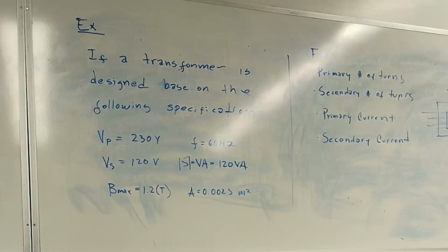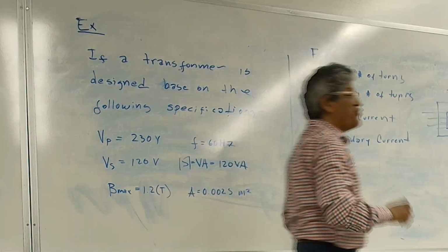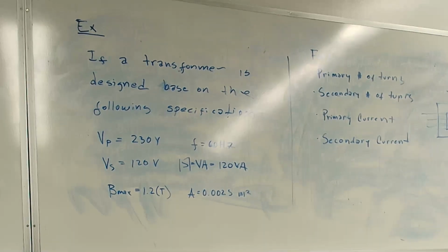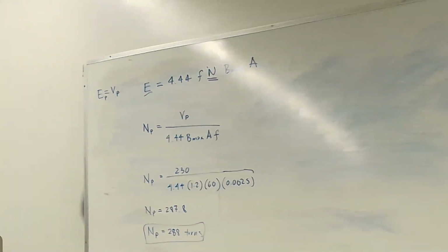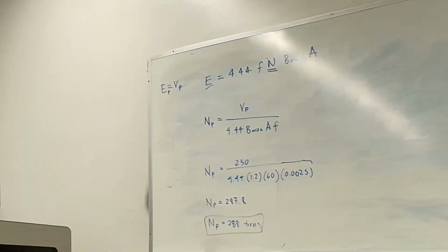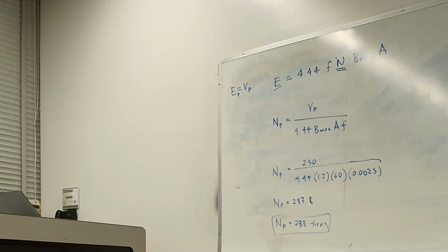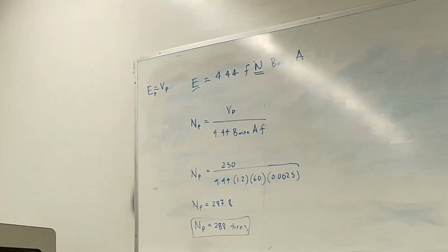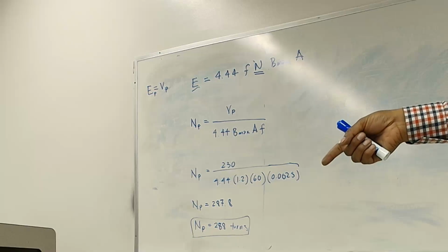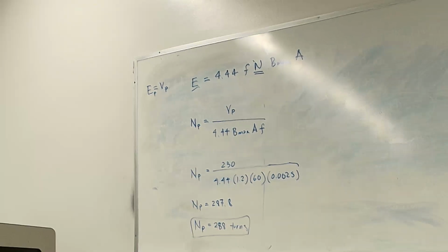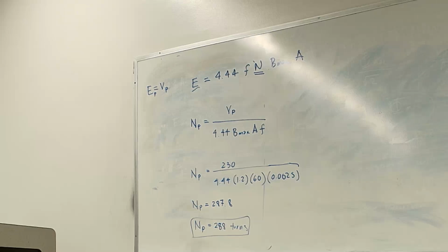Now, that's just a turns ratio, by the way. That doesn't mean that you're gonna have exactly 288. You can double it, you can triple it. But if you double it, you gotta double the number of turns on the secondary. Do I make sense? Yes. It's just a ratio. If the ratio is not maintained, then you'll pass the max. That's right. If the ratio is not maintained, well, you can think of it as this.